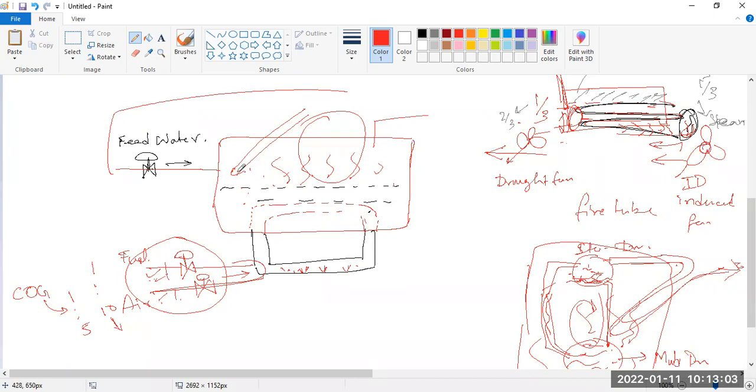If we require high pressure of this steam, then we increase this fuel and air. And if we see that this is 80% open, but the feed water is coming very high, then 80% does not work properly, so we have to increase to 100% fuel ratio.